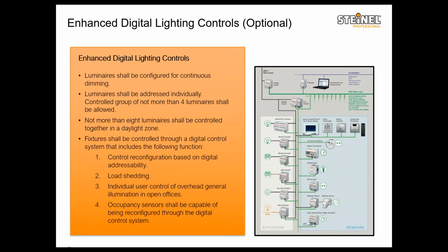As you can see, the KNX network will pretty much meet the requirements of your customers, because you have a network sensor, you have the DALI gateway to provide you with the luminaire level controls and all that. And also, since KNX is an open protocol, you can mix and match devices without any issues or any hiccups.